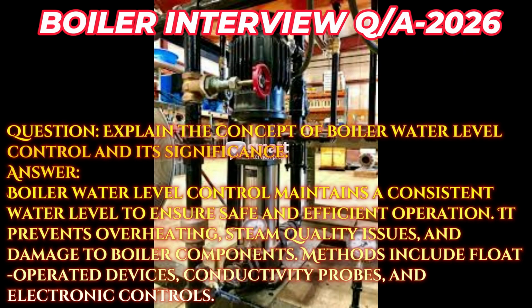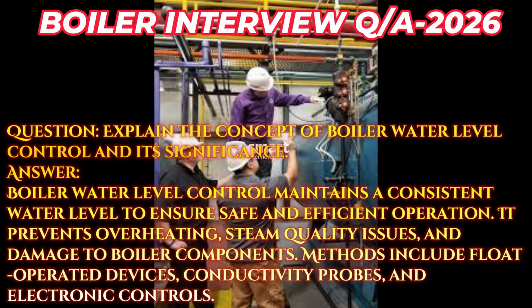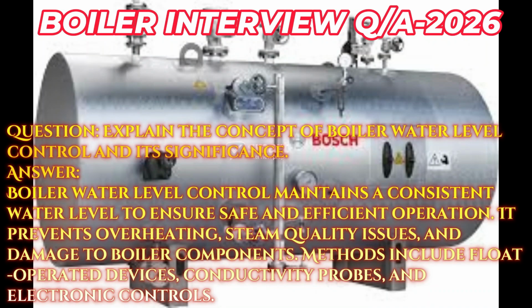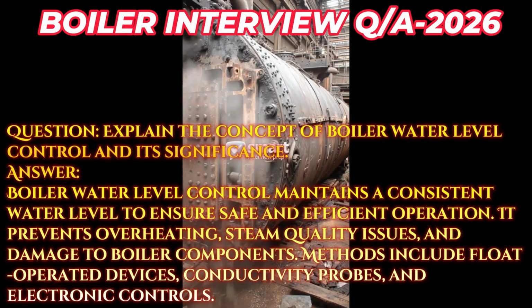Question: explain the concept of boiler water level control and its significance. Answer: boiler water level control maintains a consistent water level to ensure safe and efficient operation. It prevents overheating, steam quality issues, and damage to boiler components. Methods include float-operated devices, conductivity probes, and electronic controls.